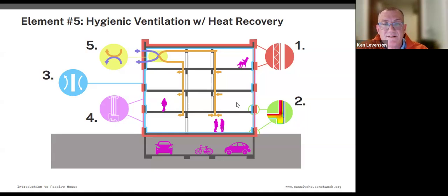We supply it. So all buildings have mechanical ventilation. They're just typically exhaust only in bathrooms and the kitchen. It's intermittent. We're relying on a leaky enclosure to bring the air through willy-nilly. We don't know if this room or that room is really getting ventilated, and it depends on the weather as to how well the building is going to be ventilated.